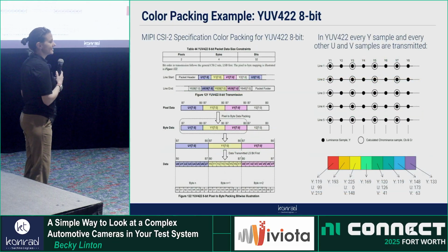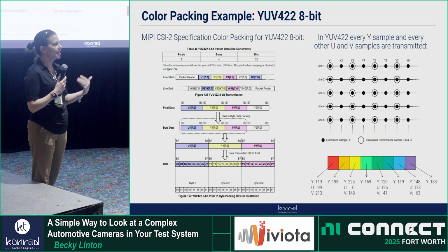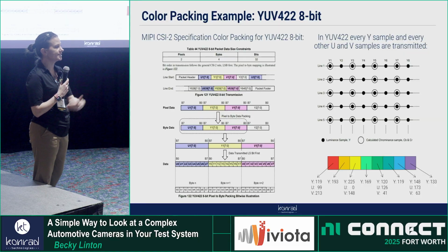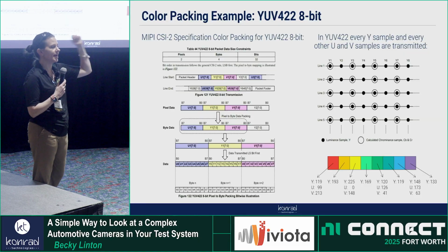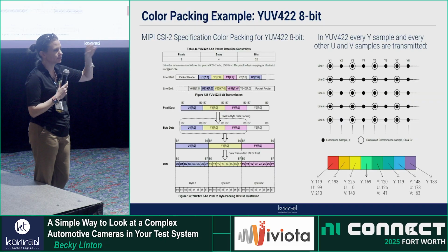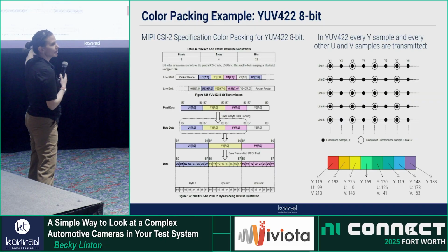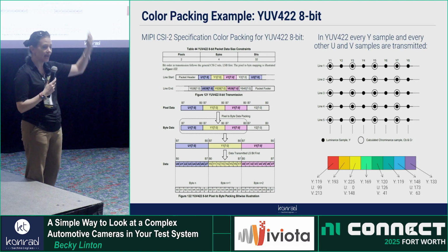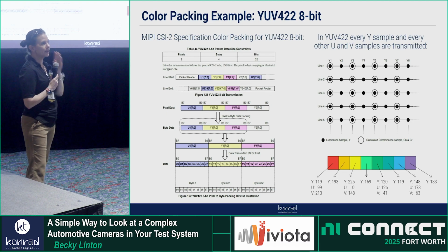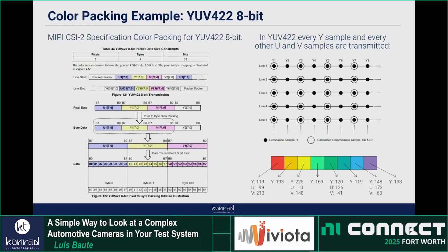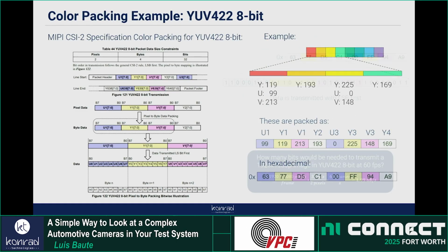So we have a RAW 16 version, a RAW 12 version, and we've written our API so that based on the camera type our customer specifies, I have a RAW 16 camera, here's my starting script. They wanted something super generic. It picks the appropriate bit file behind the scenes, which we now have to maintain a bunch of. So put in bigger FPGAs. Yeah, go through that.